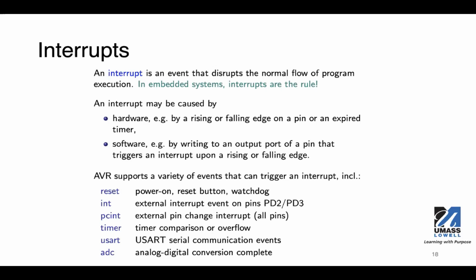Timer also can generate an interrupt, indicating the time counter expired or reached a certain threshold. And the UART or USART serial communication events also can generate an interrupt when data arrives or your transmit buffer is empty. You can put this UART in the interrupt mode to operate that way. Analog digital conversion can also generate an interrupt when the conversion is completed.